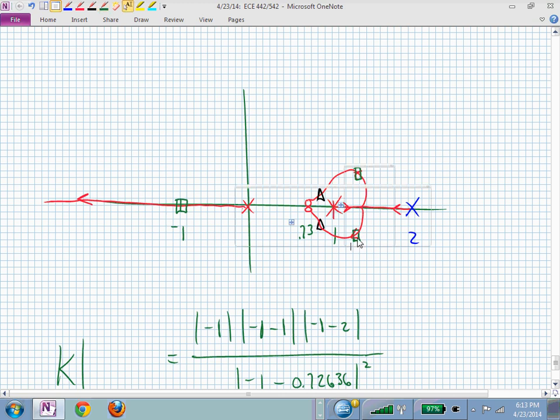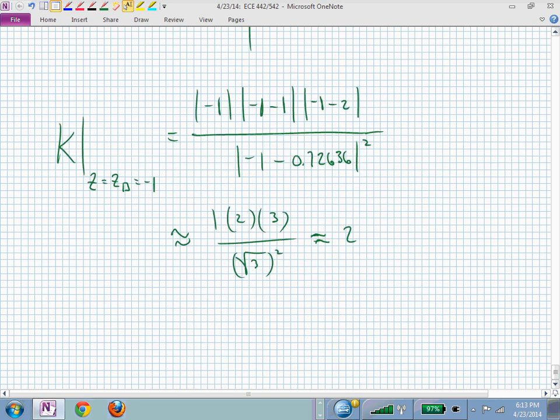Because when we crank up the gain to 6.25 is when we get to the triangle. We have now zipped outside the unit circle. We are now over here with our triangle. We don't need to know necessarily what the value is, but we know it's unstable. So that controller that we just designed is unstable.